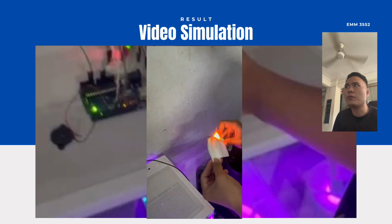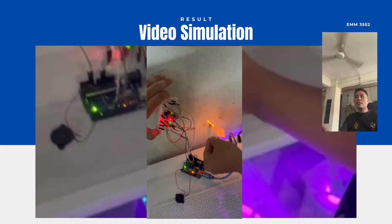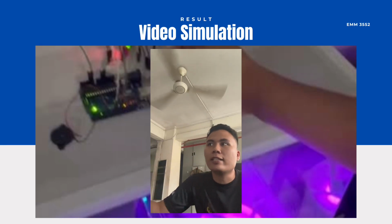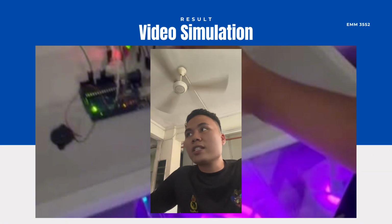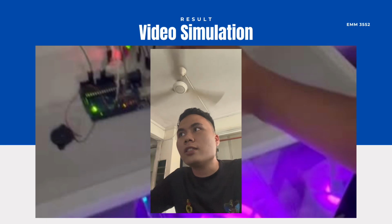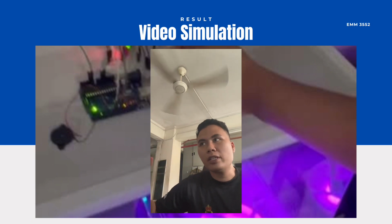So as you can see in the video, there are two types of sensor, which are a temperature sensor and the gas sensor. The temperature sensor will continuously monitor the surrounding temperature, where it will send the analog signal to the microcontroller, which is an Arduino, representing the current temperature. So if it detects a temperature higher than the predefined safe limit, such as 50 Celsius, it will activate the alert.